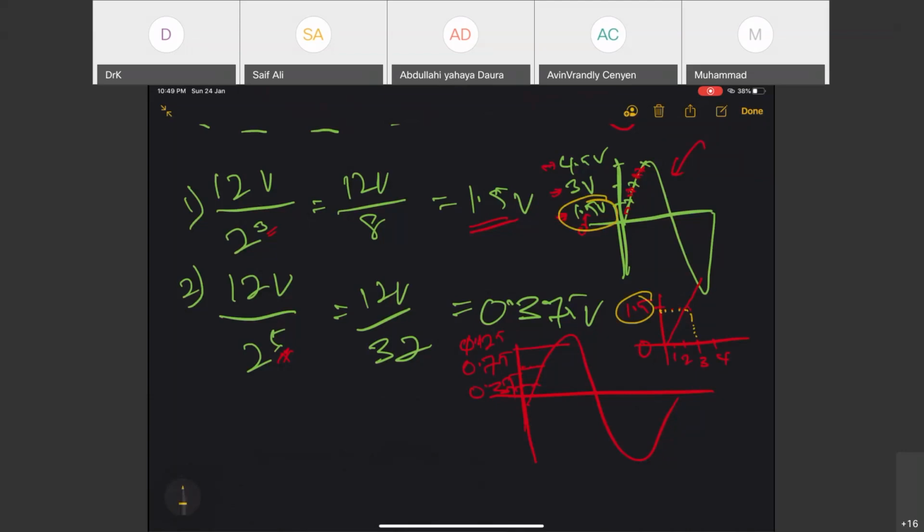Yes. You are recording from 0 second to the 4th second, but because the resolution that you are using is 3 bits here, you only start recording at the 3rd second. So you miss information at the 1st and the 2nd second. This is different from when you use higher bit resolution.